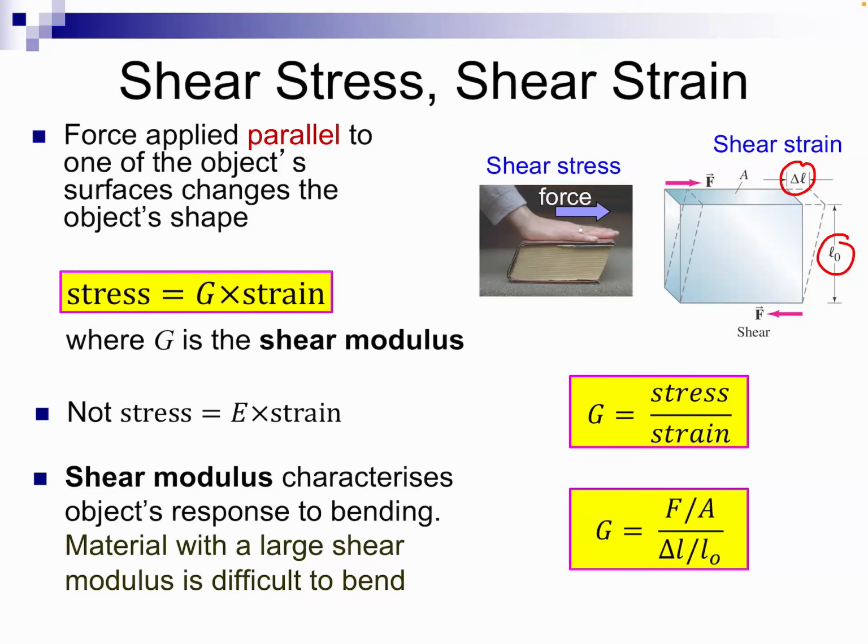And since the change in volume will always be negative, because you have final volume always less than the initial volume, this negative sign ensures that the bulk modulus will always be positive. But essentially the same strategies for calculating how much change in volume occurs can be applied as the strategy we used in the two examples for elongation with tensile and compressive stresses.